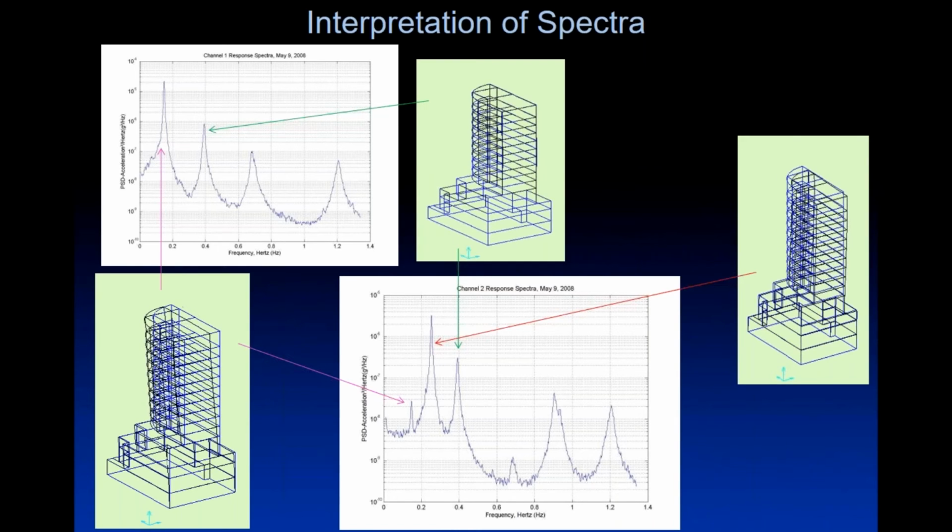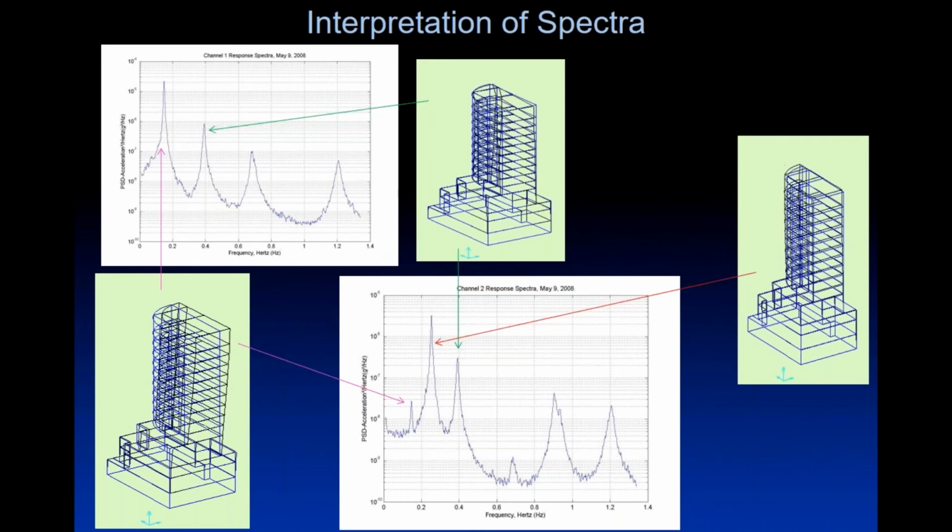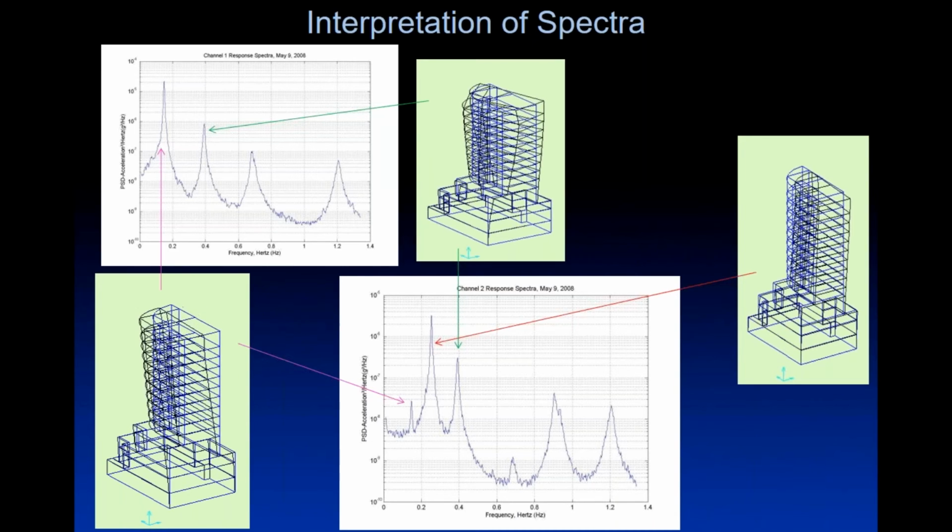So we've got the frequency shown here, which represents this mode of vibration. And now we're measuring in this direction. Let's call it the east-west direction. And over here on this other spectrum, we've got a remnant of response, again at about 0.15 hertz. In this case, that's because the mode of vibration isn't completely linear.